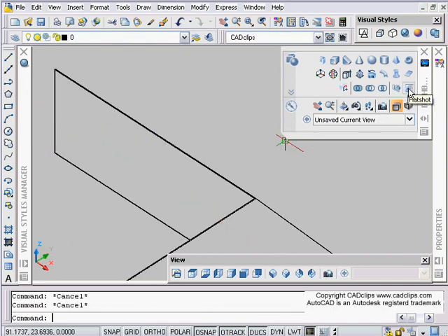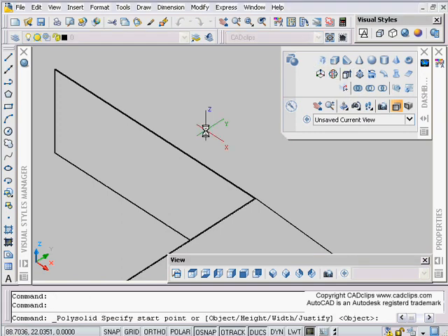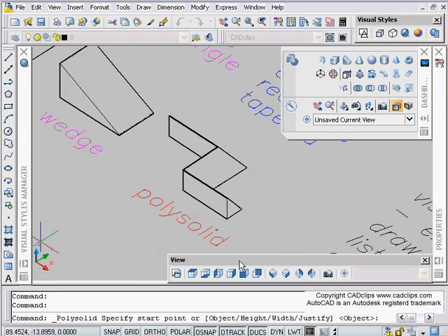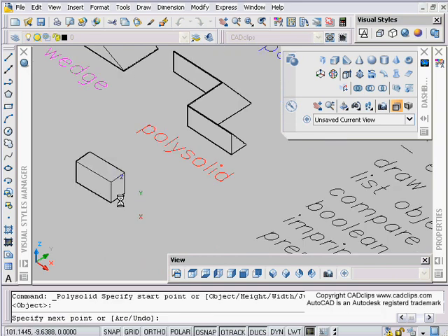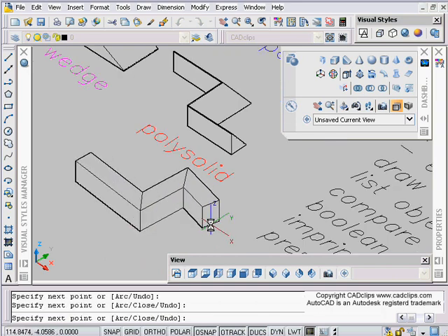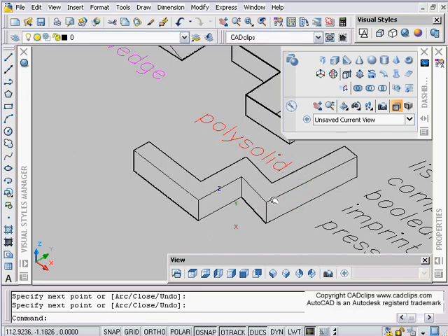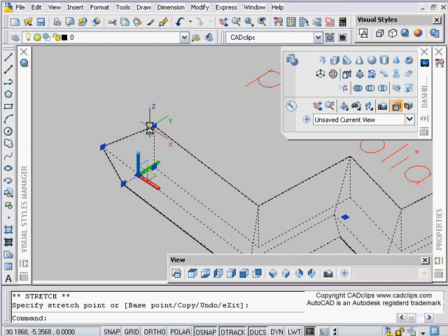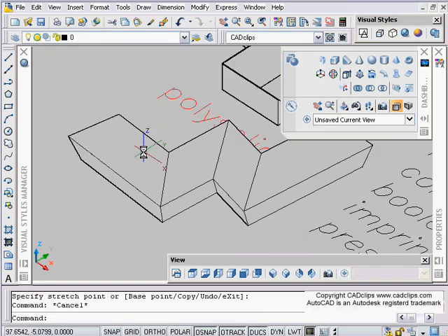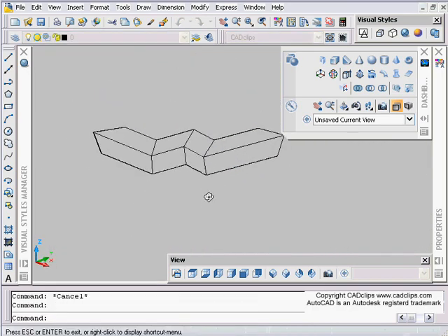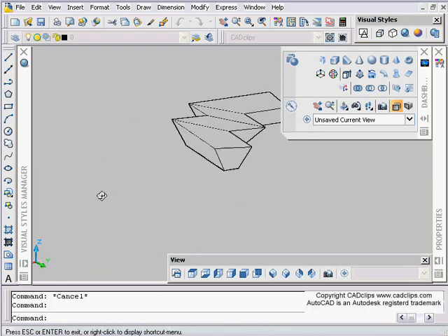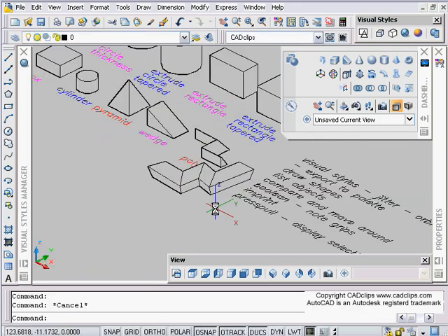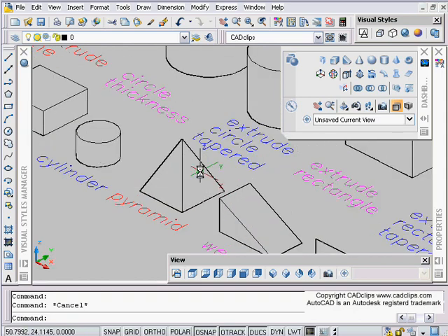We can go in and draw a new polysolid by going to, where's my polysolid command? And there it is right there, polysolid. We can say, okay, start, and we can set the width, but I think I've already got a decent width in there, so polysolid's probably one of the coolest. And remember, we have to hit an enter, not an escape on that. And then with that polysolid, we can take those grips, and using our ortho, you can do all kinds of neat stuff like that. Shift middle mouse button after we grab it. Okay, start to use some of our Boolean operations.